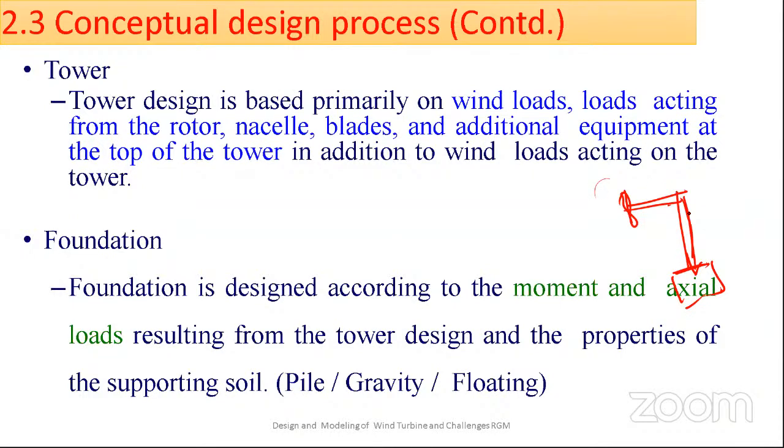Then what I want to know is what are the loads acting on the turbine. I have to know that, then only can I design my turbines, right? Because the tower I have to design based on the wind, and also based on the rotors. How much load is going to act on the rotor, how much load it's transferring to my drivetrain, how much on the tower top, and from the tower top how much load it's transferring to my tower, and how much load it's transferring to the foundation. So these loads we should know, then only we can design the turbines, right?